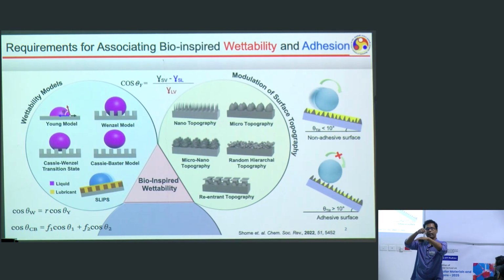Once it is in contact, you measure the contact angle, and then with a pump you can recede the droplet back. Not pulling up, it's just motorized, you are sucking the water droplet, and at the point it detaches, you measure the contact angle, and this difference is called contact angle hysteresis. Okay, the difference between the advancing contact angle and receding contact angle.